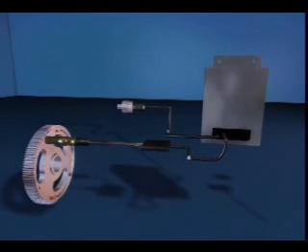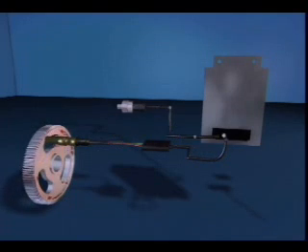The ECM uses the frequency of the signal resulting from the 6 evenly spaced cast protrusions passing the engine position sensor to calculate engine speed, and with the MAP sensor input, adjust the ignition timing.